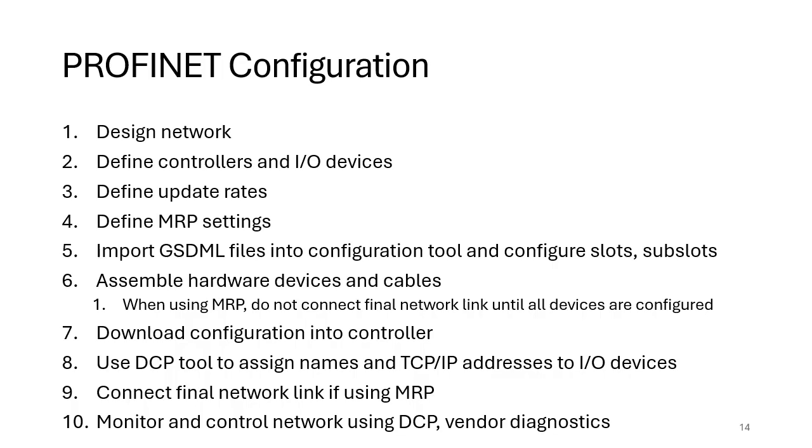So you might have two controllers or two CPUs. In this case, people say, well, what happens if the second MRM fails? Well, remember, the idea of the PROFINET system is, in redundancy, we only survive the first failure, and that includes failure of the first MRM. If the first MRM fails, then the MRCs will assume the blocked or the forwarding position, and then they will still be able to communicate. And then the failure of a subsequent device is undefined because we're really only trapping the first device failure.